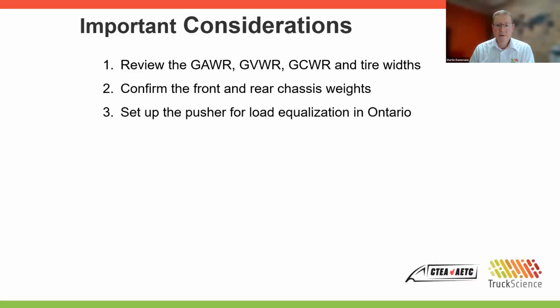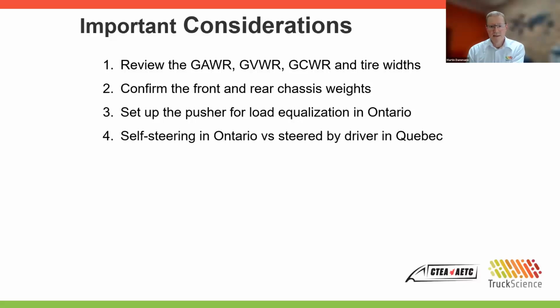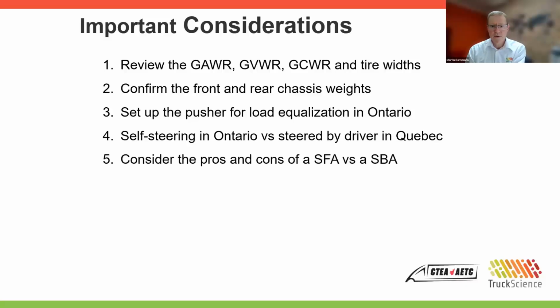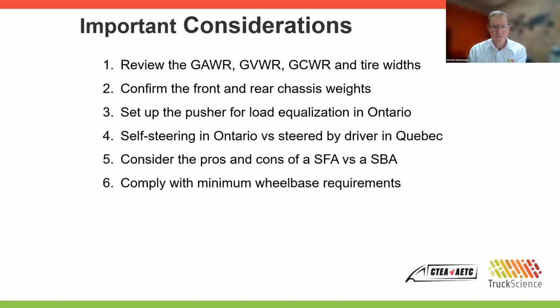For pusher axles in Ontario, decide between a Schedule 21 and 23 and make sure the weight distribution over the pusher and driven axles is set up for the required load equalization. Remember that a pusher axle needs to be a steering and lifting axle in Ontario for Schedule 21 and 23. And for Quebec, the second steering axle needs to be steered by the driver. You should also consider the advantages and disadvantages of a set forward versus a set back axle. Remember that you'll get more weight onto the front axle with a set back option.